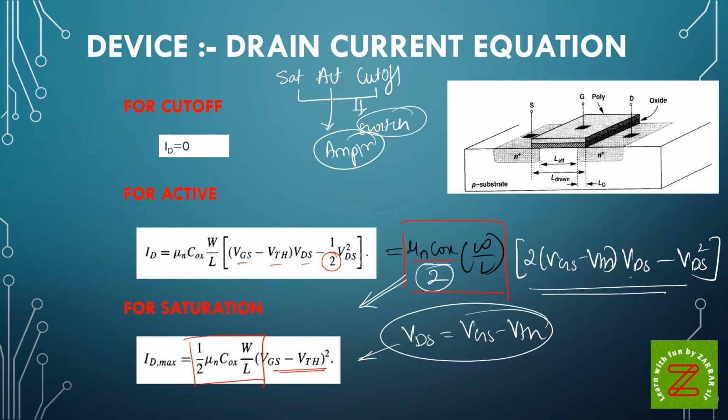So you'll get 2 times (VGS minus VTH) the whole square minus (VGS minus VTH) the whole square. So 2x square minus x square becomes x square. So you'll get this equation. So this is the equation for saturation.